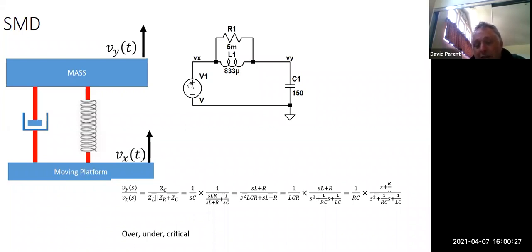And you can see that by finding the natural response, short out that power. I can go power supply, I can go through the inductor to get to ground. I can go through the resistor and get to ground. I can go through the capacitor and get to ground. They're all in parallel. So ultimately, it's that parallel structure, 1 over RC, but the omega naught squared is still the same term. Now, how did I do that? I found these in parallel and then used voltage division.